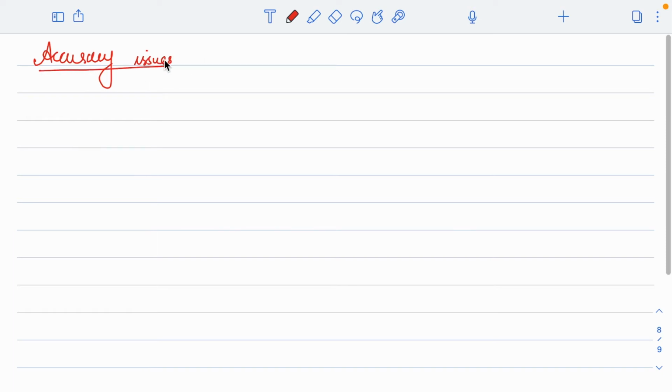Let us quickly look at that, right? So there are several things that come into picture. The one important thing is we are using a string of resistors, right? As we have discussed in resistor string DAC, the matching of resistor string is very, very important, or the accuracy depends on that too, matching of the resistors. And if you remember, in resistor string DAC we have considered mismatches in different ways, right? We considered that for the lower half you have positive mismatch, the upper half negative mismatch, so the middle point will be a point where you will have, so those things we have considered. So we'll do this in the same line as what we have done over there.